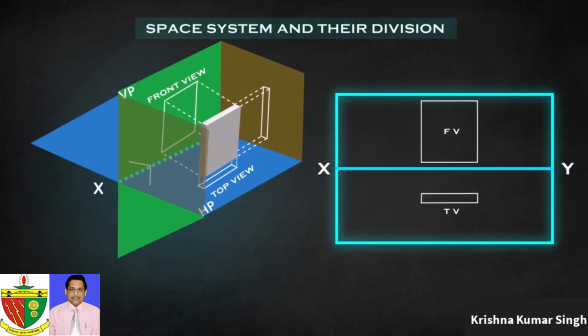Now, you may get a doubt about side views. Where can we draw them? Well, we consider another plane, which is perpendicular to both HP and VP. This plane is called the profile plane. The side views of the object are projected on profile planes. The left side view is displayed on the right side profile plane, and the right side view is displayed on the left profile plane. The left side view should be drawn right side to the front view on drawing paper. The right side view should be drawn left side to the front view on drawing paper.